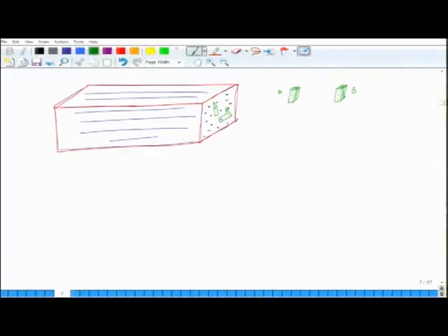Now, because I have cut the material in a very special way, if I pull it in this direction, both for sample A and sample B, remember the direction of the samples for A and B was different. This direction is oriented like this, and here the direction is oriented like this, but in both the cases I made sure that the length of the sample lies in the plane of this end plane, right. And then if you test this material in tension, sample A and sample B, you will find that their material properties are the same, and you will also see that if you just pull it, it will only exhibit extensional strain. If you compress it, it will still exhibit only extensional strain. If you apply shear to it, it will exhibit only shear strain. So, this is one plane.